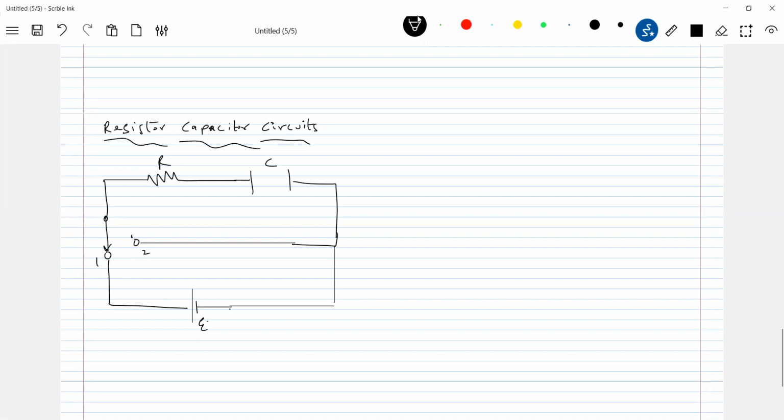And what is the capacitance? Capacitance is not something intentionally brought into the circuit. It can be unwanted capacitance. Unwanted by whom? Any conductor will have capacitance. Don't think that only if you bring a capacitor into the circuit there will be capacitance. Unwanted capacitance will be there. What is unwanted capacitance? Because what we concluded is that any conductor will have capacitance. That's why you got some numericals in the exam also.